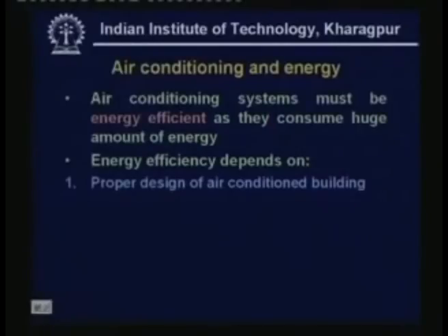It depends upon the design of the air conditioned building itself. For example, if the building is not designed properly, then it consumes a lot of energy. Nowadays you might have seen that a lot of people use a lot of glass. The use of glass leads to larger loads on the air conditioning system. That means you require a bigger air conditioning system, which will ultimately lead to larger energy consumption. So here the architect has a role to play.